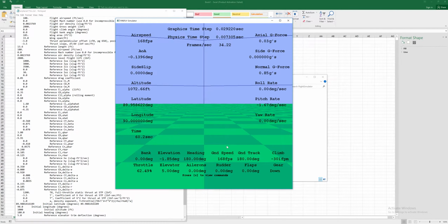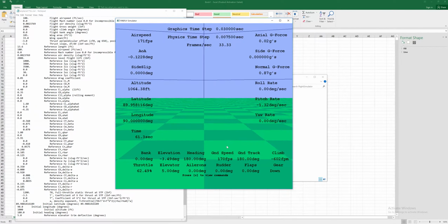Okay, so you can see the aircraft pitch up sharply, and the stick is back at 0, by the way. I just hit it quickly, and so we saw the aircraft pitch up, and now long term it's going to go into a phugoid mode. We're going to be able to plot this afterwards. It's recording this data as a function of time, and so we're going to be able to go back and plot this and look at the mode in a little bit more detail. So we'll just let this run for a second.